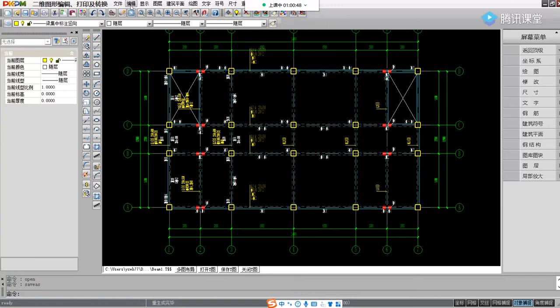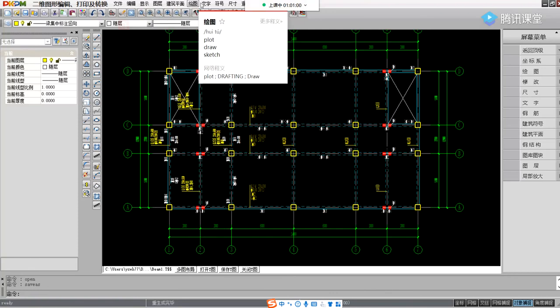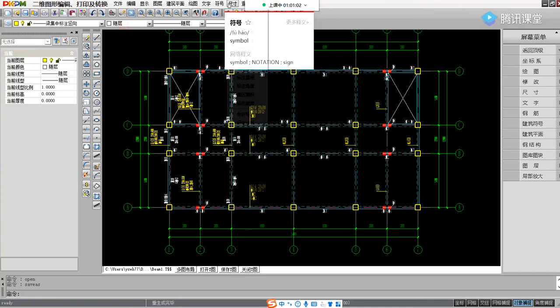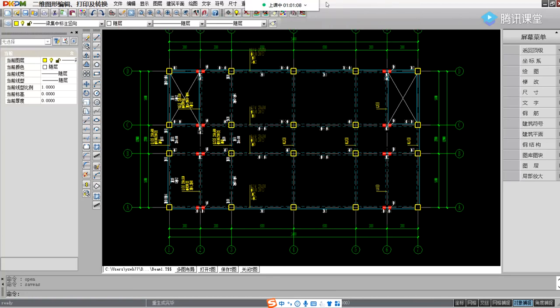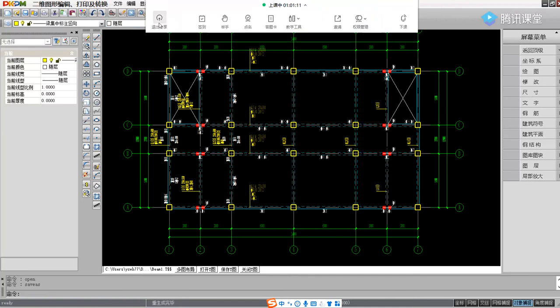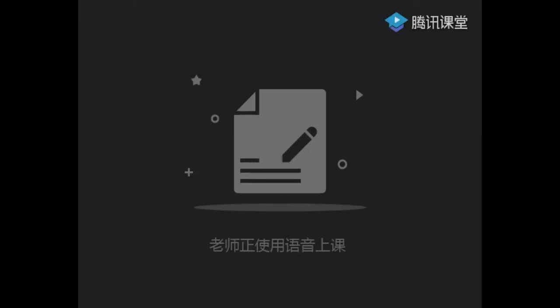It has a transformation, a T to DWG one. This thing is really annoying. Oh, here. Yeah, it's in the menu. In this menu, Tools, then we click it and we can see the first one and the second one are both T transform to DWG.